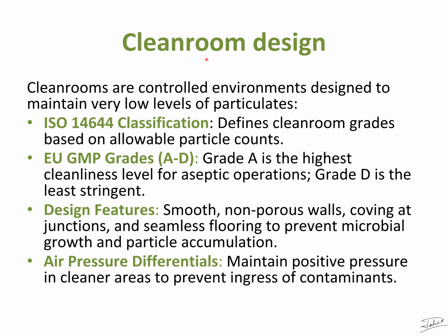So clean room design, in our HVAC system chapter, we have already discussed this. Clean rooms are controlled environments designed to maintain very low levels of particulates. ISO 14644 classification, we know from 1 to 9 classification. EU GMP classification from grade A to grade D. Then design features: smooth non-porous walls, coving at junctions, seamless flooring to prevent microbial growth and particulate accumulation. Then air pressure differentials maintain positive pressure in cleaner areas to prevent ingress of contaminants.